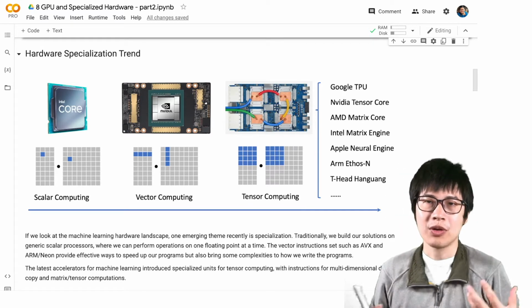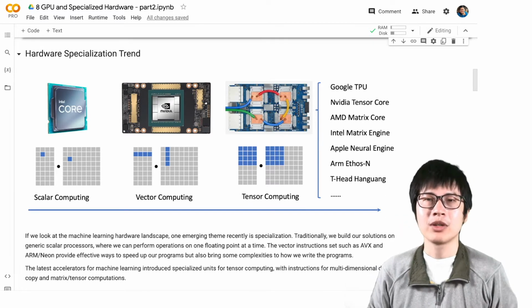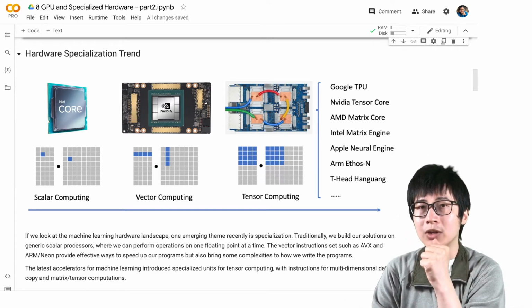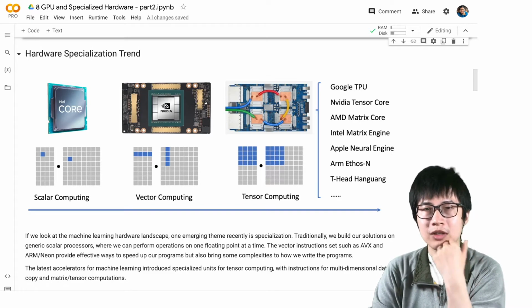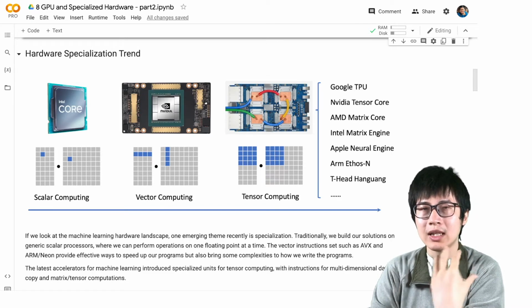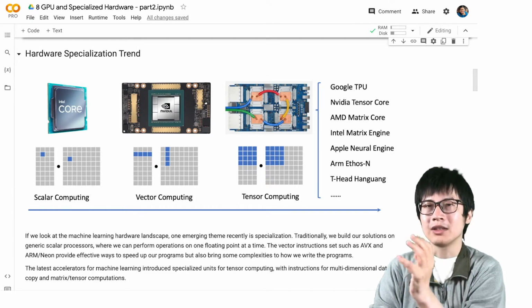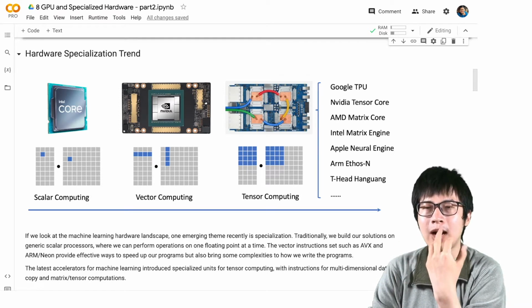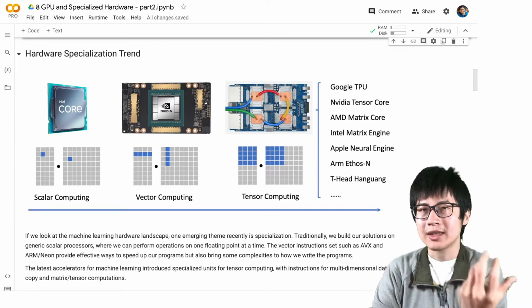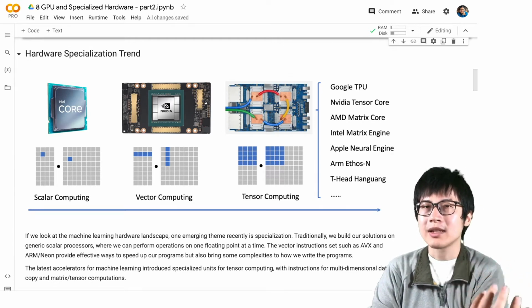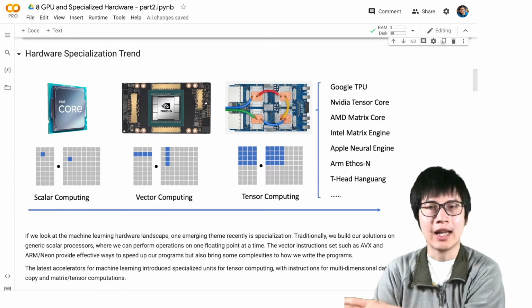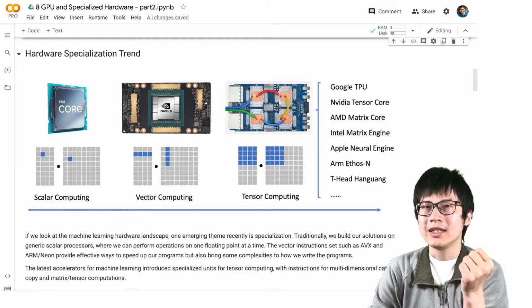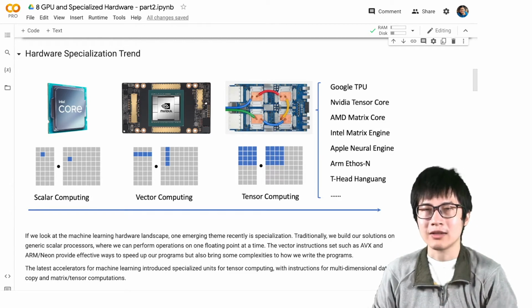So one more question we want to ask: how can we build a machine learning compilation process for these kinds of specialized hardware? One interesting thing about specialized hardware is that each kind of hardware is different. One hardware backend may contain a 16x16 matrix multiplication instruction, and a DMA unit that allows you to shuffle in data in units of 1024.